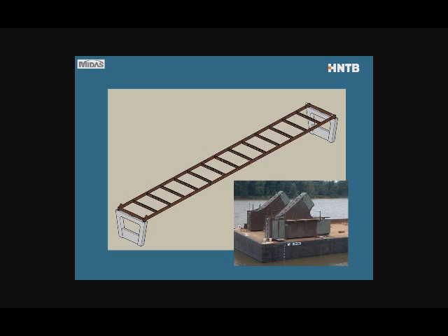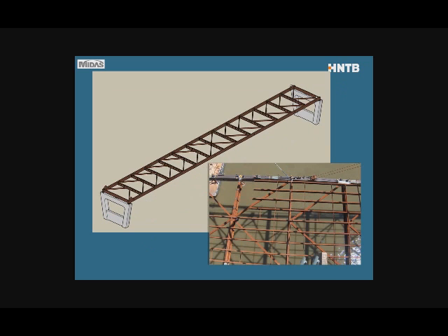You can also see at the end of the front knuckle joint, those gray patches. This is where the end floor beam is bolted into the knuckle joint, and it needed a lot of bolts just to transmit the jacking force when the jack is applied. So a very, very complex joint, but it's crucial for the structure. It's also through that joint that the arch rib gets stabilized a little bit.